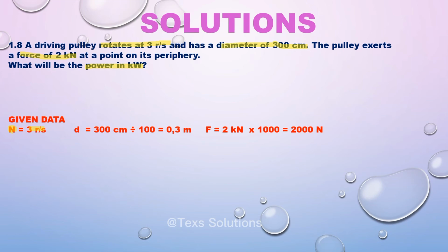If you see the word rotates, it means we are dealing with an object that is spinning or rotating. In other words, we are dealing with angular motion, like the wheels of a tire, right? The units of measurement for angular motion are very different from when it is moving linearly on a straight line. That is why we are using n, which represents the rotational frequency. d is my diameter, which is 300 centimeters. The correct SI unit is meters, so I'm going to convert from centimeters to meters by saying 300 divided by 100, which is 0.3.